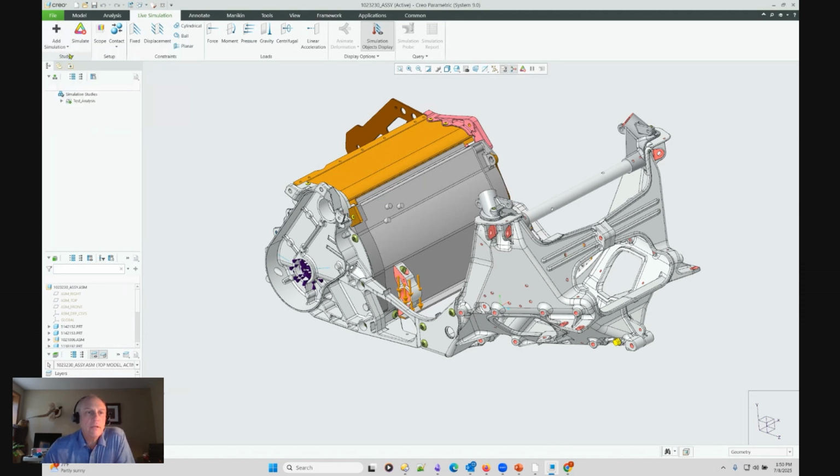The other thing I would show you here is when we're actually in the study, you have the ability to toggle the performance, right? So you have just a slider here that takes you between a higher speed, quicker to run simulation as opposed to a little bit more accurate, right? So you have the ability here to just use that slider to toggle between the range of the simulation quality that you're interested in, right? So you can go ahead and just modify that as needed.